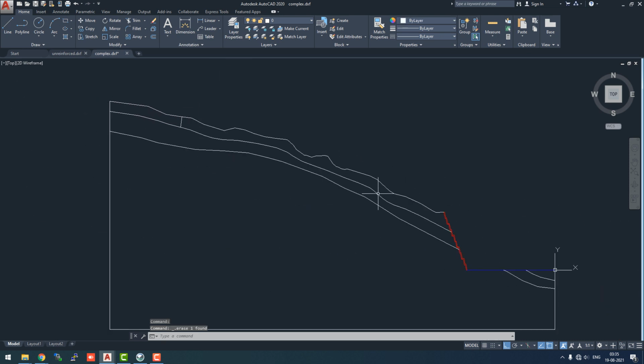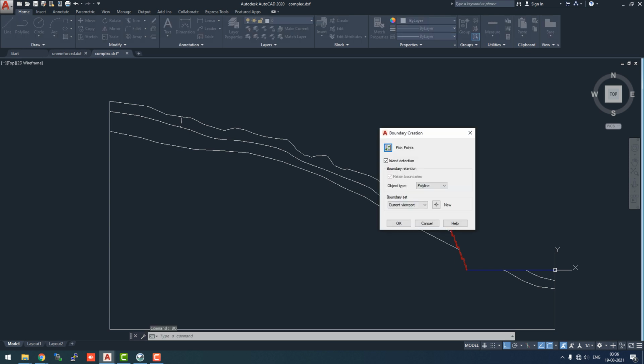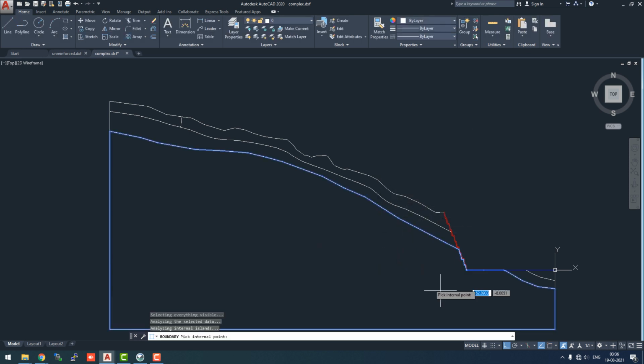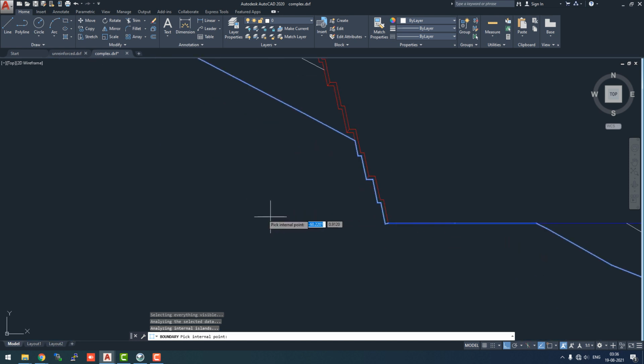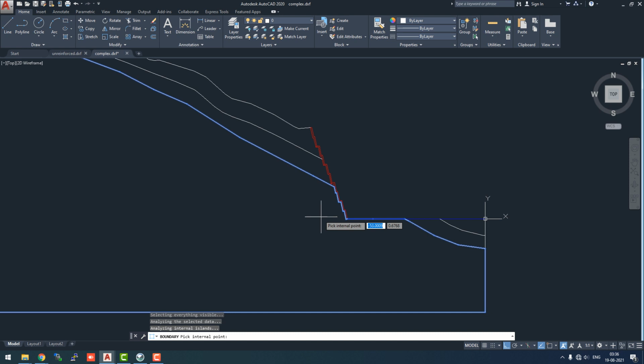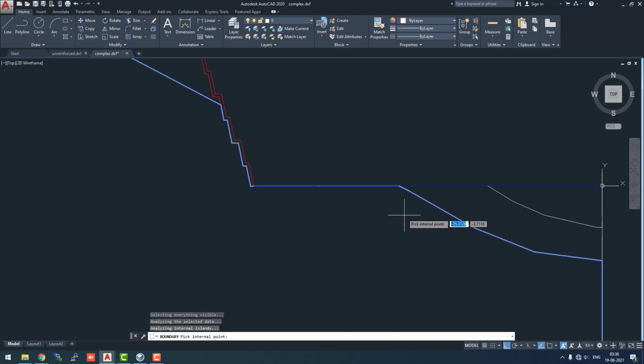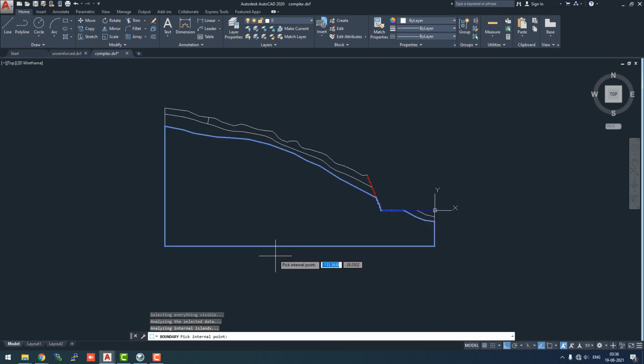So what we can do is that we can now create the boundaries of each of the enclosed regions. So we'll just click on the command line, space bar where we can type a command. We'll go and type BO and we'll click on boundary. We'll basically use the island detection technique. The bottommost part will be again rock. So you can see, and you can go into it and clearly see that what we are doing is not wrong. So we'll just click on enter.